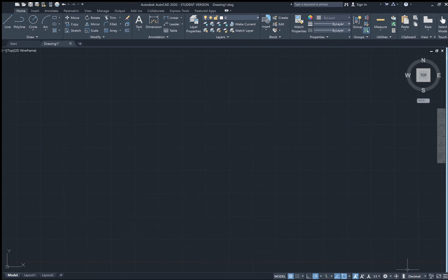First off, let's start down here. There are quite a lot of different types of settings for your document, and these are all very important to start with. The first thing you want to do is establish your units, because like any drawing, units are very important. Units come in architectural, decimal, engineering, fractional, and scientific. For the purpose of this tutorial, we're going to use the engineering units. As you can see, it's specified in inches.